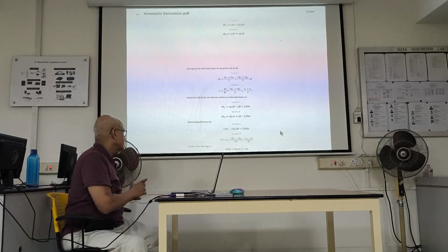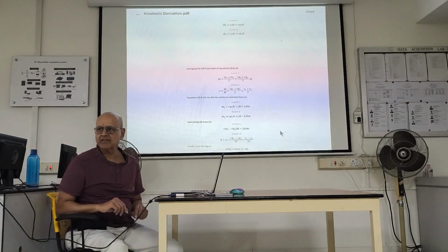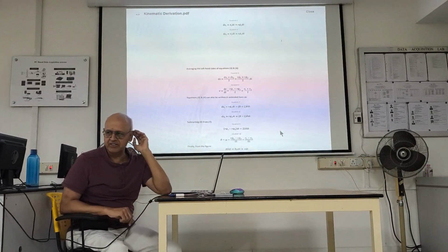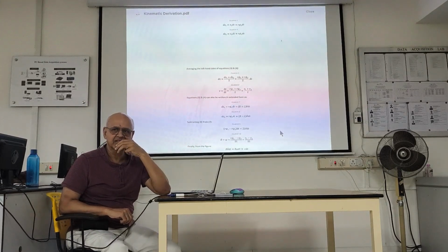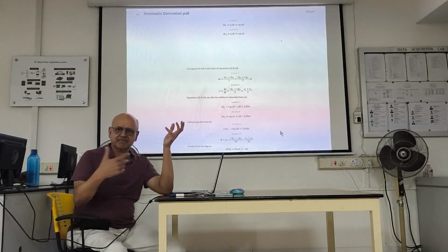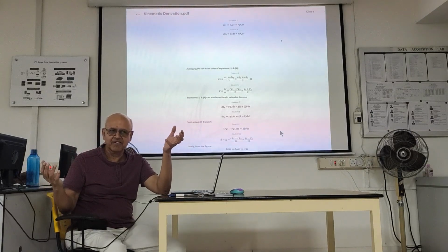Just to make sure you understand this, I'm going to ask you a few questions. Okay? Right wheel and left wheel are spinning at the same velocity. What is omega? Zero, right? What is the average velocity? Either one, because it's the same velocity. V1 plus V2 by 2 will give you V, right?